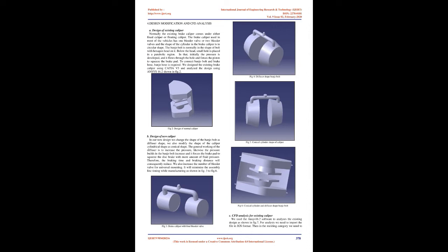To overcome this problem, small titanium blocks can be used in between the backing plate of the friction pad and the piston surface. The 5 most important characteristics that are considered when selecting a brake pad material are as follows. The material's ability to resist brake fade, the effects of water on brake fade. All brakes are designed to withstand at least temporary exposure to water, the ability to recover quickly from either increased temperature or moisture. The materials used for brake pads are non-metallic material, semi-metallic material, fully metallic material, and ceramic material.